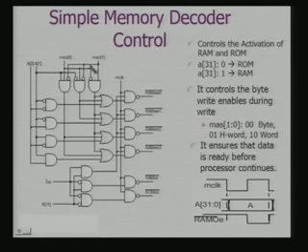So, that is why the size signal becomes important, and this is coordinated with your MCLK signal, because all these things have to be valid, ROM enable when the address is valid, and this signal gets validated with respect to your basic clock which is driving the system.